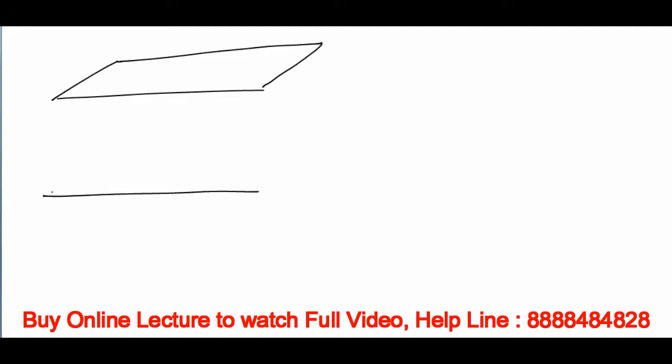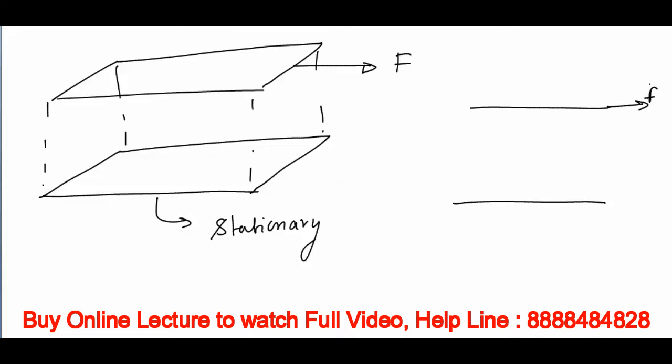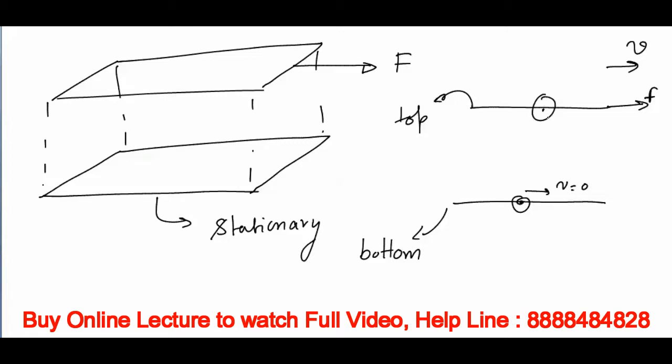It means that, let me take a case where I have two parallel plates. If I show them in 3D, it will be looking like this, and there is fluid in between. If this plate is stationary and this is being pulled by a force F, I have fluid which is sandwiched in between. So if I see a 2D diagram, I have a force F. Because of force F, there will be certain velocity V of the top plate. This is my top plate obviously, and this is the stationary bottom plate. Now this is stationary, so velocity of the fluid near this surface will be 0. Velocity of the fluid at the top will be V.